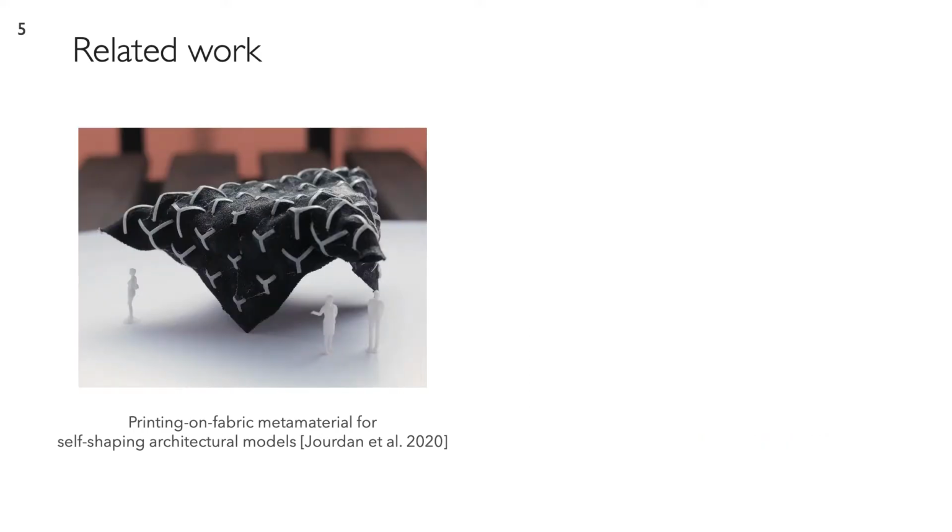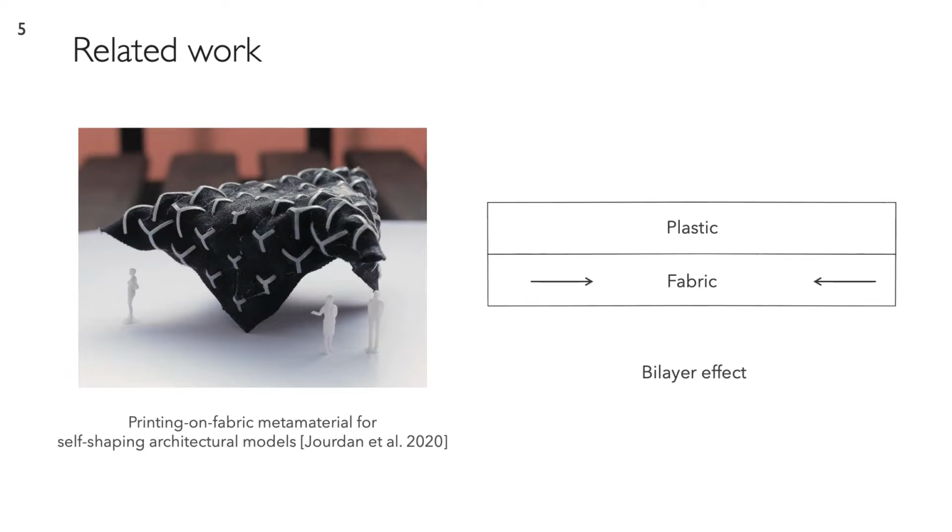In a previous work of ours, we showed it was possible to obtain convex surfaces with positive Gaussian curvature by printing small and disconnected elements instead of closed curves. We also highlighted the importance of modeling the bilayer made out of a stiff plastic layer on top and the